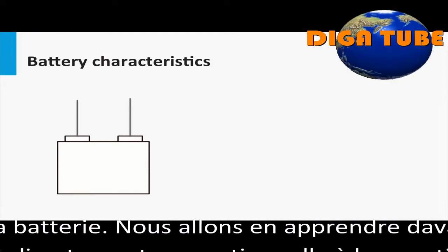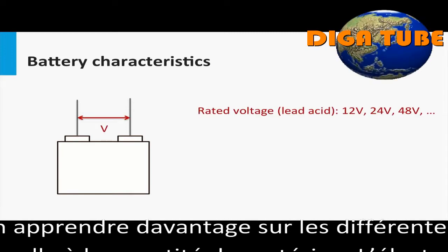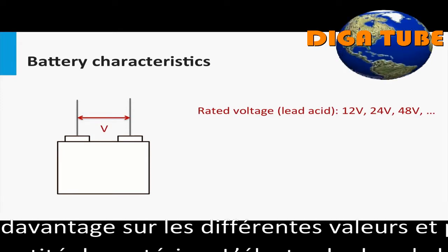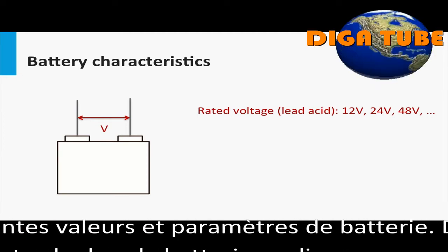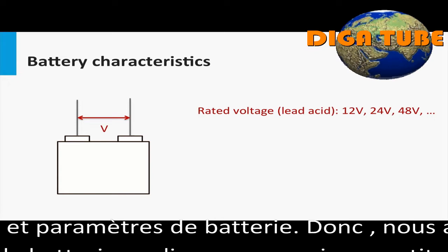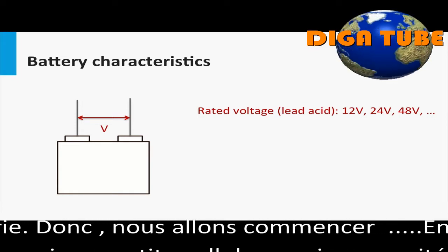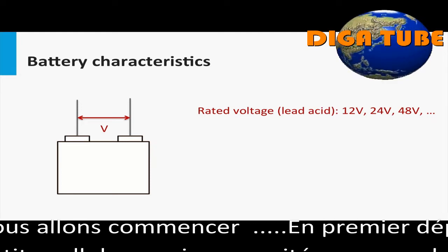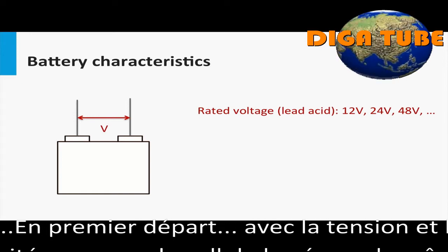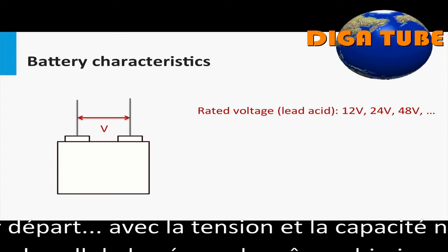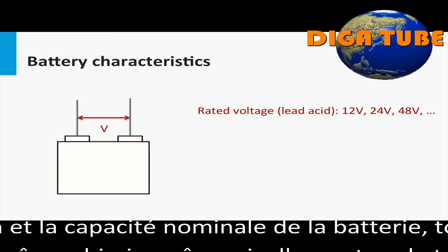Every battery is rated with a certain voltage and capacity. The battery rated voltage is the nominal voltage at which the battery is supposed to operate. The so-called solar batteries or lead-acid grid plate batteries are usually rated at 12 volts, 24 volts or 48 volts. Of course, the battery system in your PV system can attain any voltage based on the interconnection of several batteries